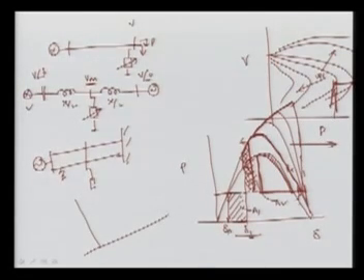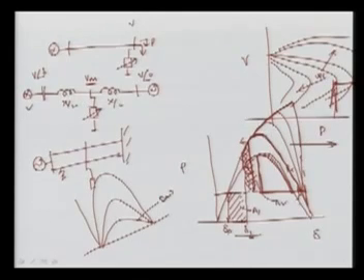Here what will happen, now this is again your P-delta curve, that is called the post-disturbance fault. In the pre-disturbance, before that, we had this much. During the fault, we can say this one. So this is your during fault. This one is your post-disturbance, and this is your pre-disturbance. Why pre-disturbance condition? Because the system was healthy. Here, when there was a fault, this machine was oscillating, and we had this characteristic.